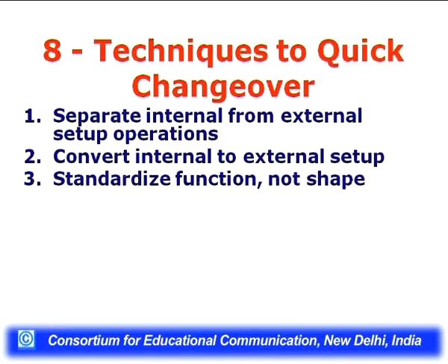Convert internal to external setup. Let me explain the difference between external operations and internal operations. Internal operations are those operations which are done on the machine when it is not running, and external operations are those done while the machine is running. So, this is the difference between an internal operation and an external operation.